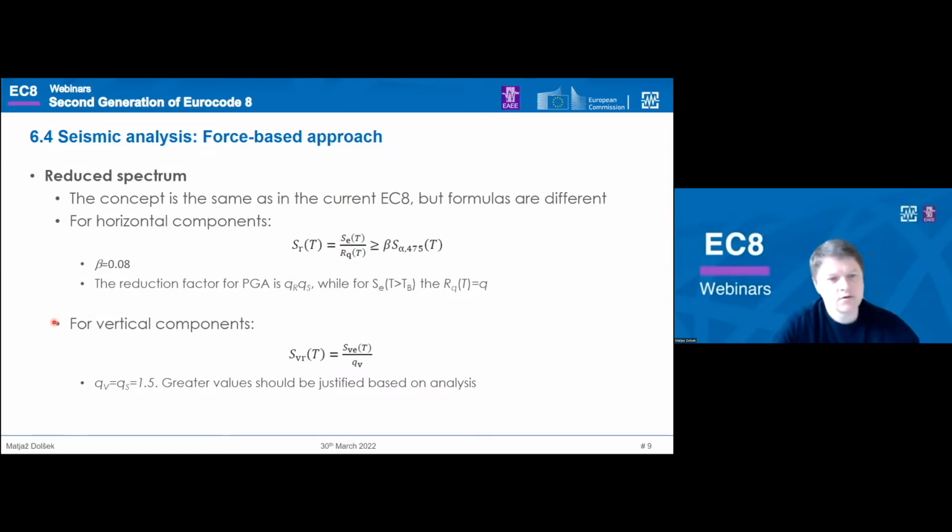And for the vertical component, we can consider the behavior factor equal to 1.5, and greater values should be justified based on analysis.